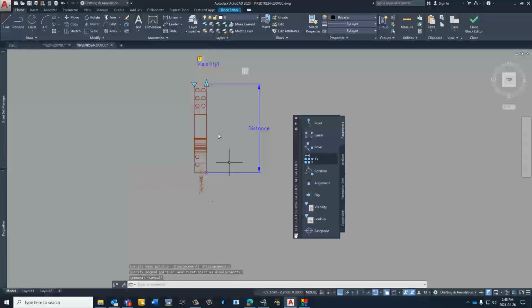This is going to give me then a block that I can insert into the panel and be pretty confident it's going to have a similar layout. The other thing that I need to incorporate on here is a wipeout. Remember, this is a 2D panel block. It would be inserted over a 2D arrangement of DIN rail. So what I must do is make sure that we don't have to do all the deletion of the DIN rail blocks as much as possible.